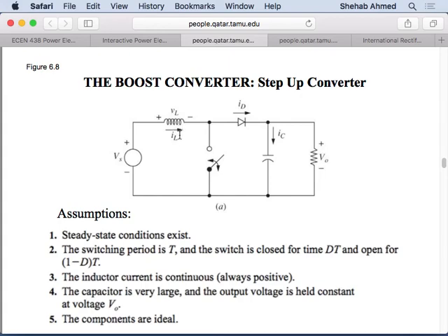What's your question about increasing resistance? I'm now saying if I put a resistance here in series, and I increase my duty ratio, we agreed that I'm storing more energy. If I'm storing more energy, I'm able to boost the voltage on my output.